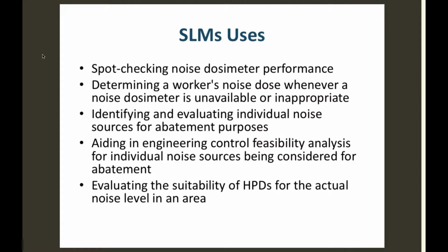Okay, spot checking the levels of noise that are present, and also checking the levels of noise that are measured by a dosimeter in the vicinity of his head. Basically, when you take sound level measurements, you're considering a 2-foot sphere around a person's head. So you would have an instrument or a microphone that might be on his collar or on a device that he's wearing on his head, so you can take sound level measurements right in his hearing environment.